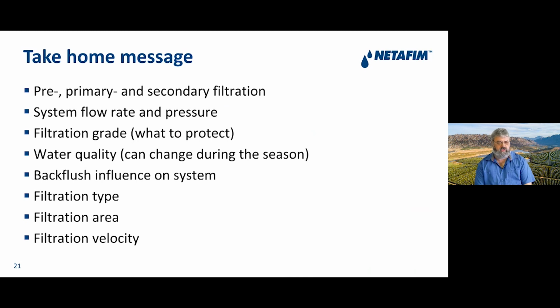So that's important. The system flow rate and pressure, this is something that we need to understand because it will have a very high impact on the design of the filtration. Then filtration grade, what do we need to protect? And then we will make that selection.